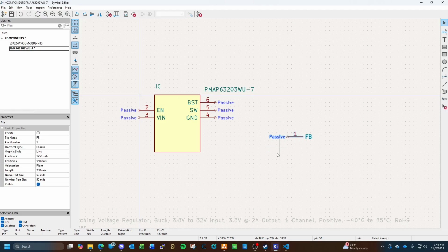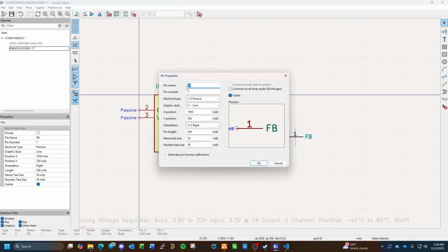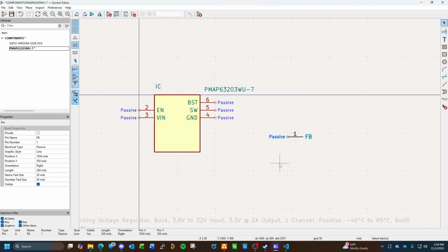I know it's crazy, but if KiCad works the same as Altium, the way the pins are organized here on the screen doesn't matter as long as their designator, pin number matches properly to the footprint. Then it'll line up properly in the actual PCB layout. So I'm just going to assume that KiCad works the same. There are reasons for what I'm doing, and it sounds crazy. It seems crazy.